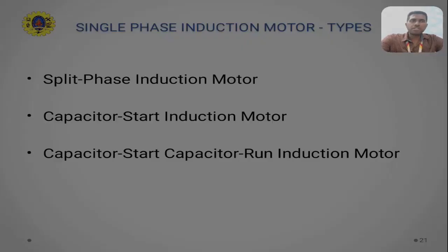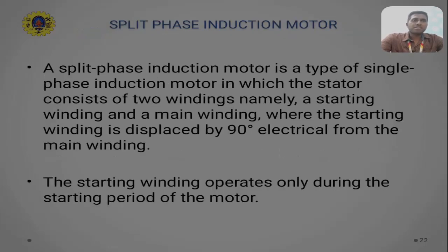So next we are going to see about the types of single phase induction motor. There are three types: split phase induction motor, capacitor start induction motor, and capacitor start capacitor run induction motor. So the first type is split phase induction motor.